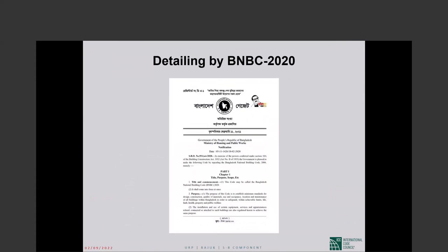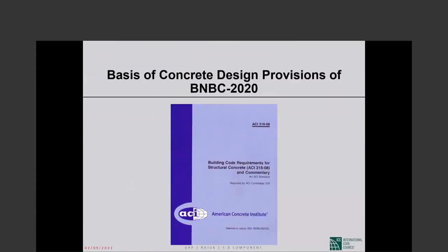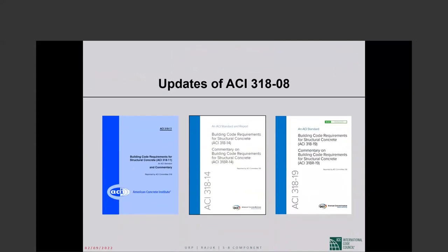Our basis is BNBC 2020, as with everything else. And I think it has been mentioned repeatedly during the concrete sessions that the basis of the concrete design provisions of BNBC 2020 is ACI 318-08. Okay. Now, after 318-08 until now, we have had three editions of ACI 318: 318-11, 318-14, 318-19, which is the latest.